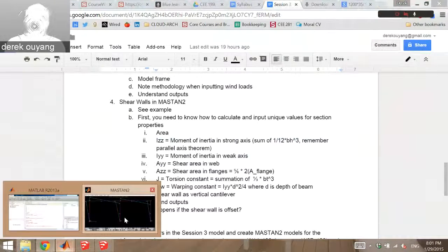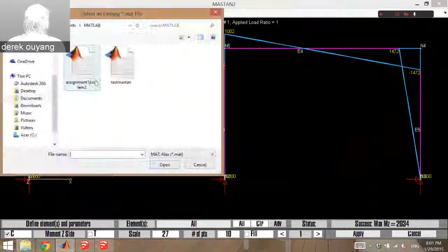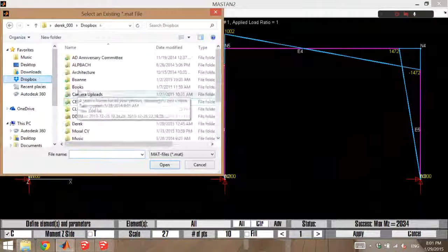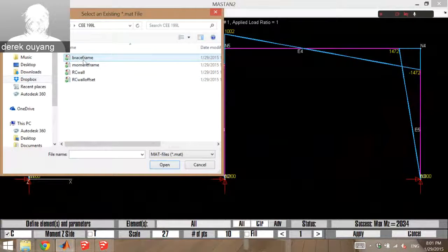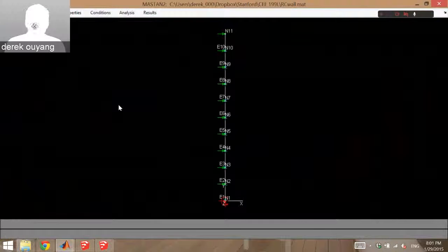So actually, I'm just going to open up right now to do a full model somewhere in here. Does that make sense to everyone? Why you can just model it like that? So you don't care at all about the shape of the shear wall. You just know that it has a rigidity in one direction and a rigidity in the other direction, which is your moment of inertia I in two directions, right? Yeah, it's just going to go straight up. Actually, it's going to be 3 because the third one is whatever you design yourself, which can be a shear wall with different dimensions. It could be a moment frame with different dimensions, but I do encourage you to try something more inventive.